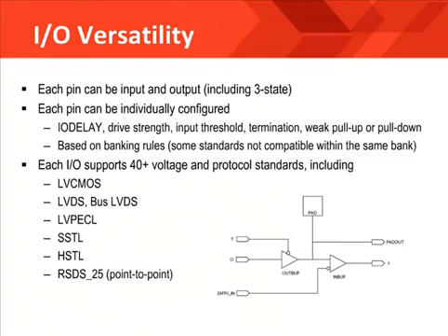The SelectIO feature allows direct connection of the FPGA pin to external signals of varied voltages and thresholds. This optimizes the speed-noise trade-off and saves you from having to place interface components onto your board. All the dedicated interface logic already exists and can be selected on a pin-by-pin basis. However, note that to mix different I/O standards into the same I/O bank, you must be aware of the I/O banking rules.